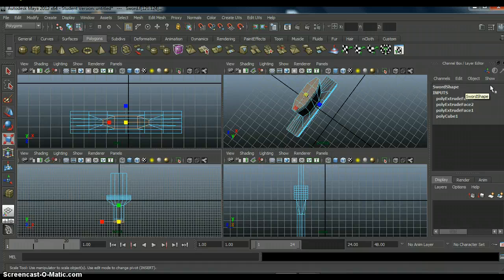And I would like us to once more scale the bottom handle, and I would like to scale it on all axes. So let's pull on the middle of the box, I should say, and that should do it. Alright, use the rectangular prism in top view to use it as your reference point. That way you know where to stop, and there you go.